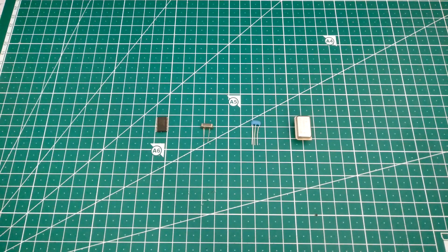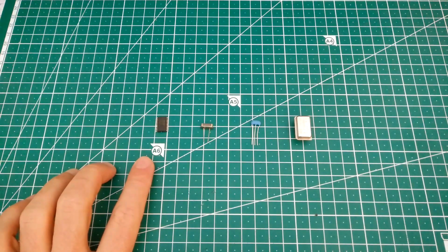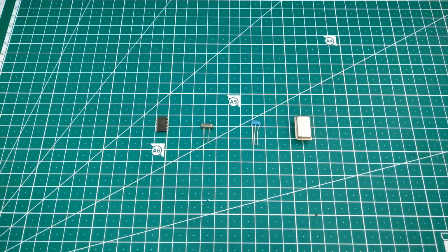Here you can see 4 different ways to provide a clock for your microcontroller in your custom circuit. The first one, which we've covered already, and here symbolized by an actual microcontroller, is the internal oscillator. The internal oscillator is built in and will work directly without the need for any external components. Now, whilst the internal oscillator might sound like a perfect solution, it has its own limitations.